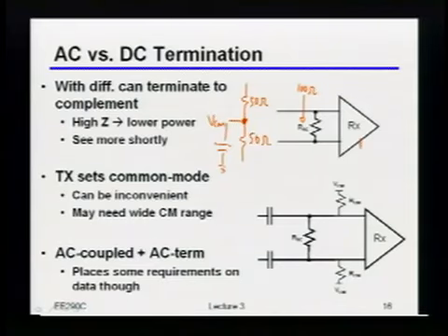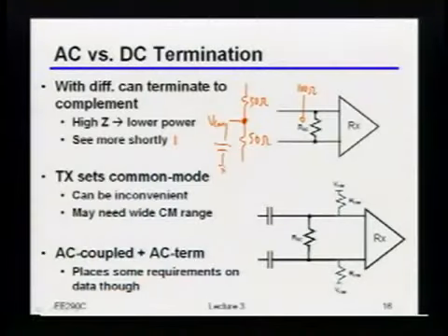Any other, by the way, very practical reasons why that might be a little bit annoying? You might want a low swing at the transmitter to reduce power. Okay, so which means your common mode will be pretty high. It could be, it depends on how you actually do it, but yes. Compatible with the receiver side. So what you said was, if I have my transmitter over there and I want the swing relatively low, that may make the common mode very high, and that common mode may be bad for this receiver.